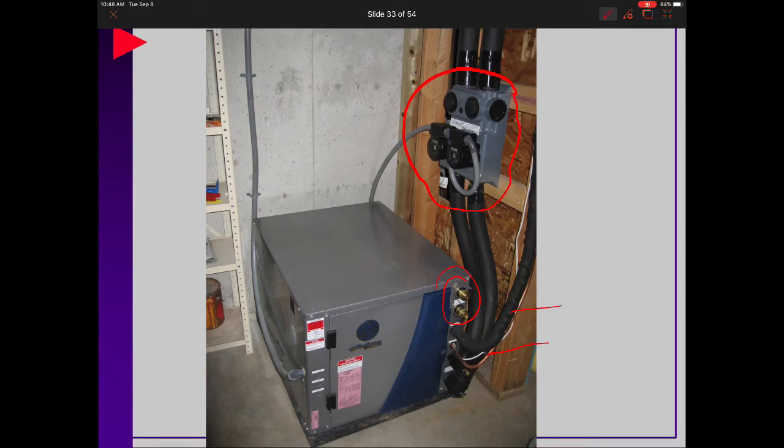They're using a couple of pumps, one to push the water in and the other one to pull the water out and push it back into the loop field. And that's all done with your flexible lines. Typically they could be done with copper, but a lot of companies will end up using the flex lines. But nice little split system. And then this would go to an air handler that's separate. So you can do it very similar to a normal conventional system. We have some contractors in the Northwoods that actually do this a fair amount.